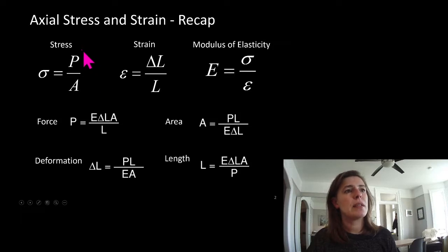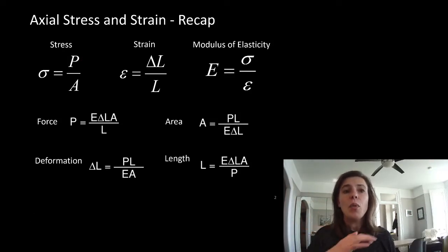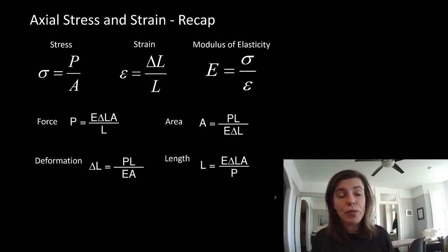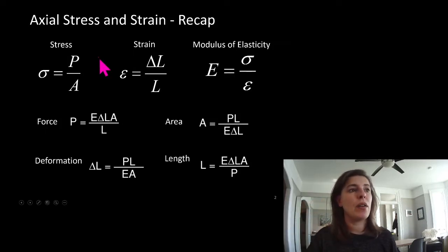Same here with stress. We want to know the force. Last term, we knew we could figure out what the force on a column is. We find the tributary area. We find the loads that are acting on the floor from our load tables for dead loads and live loads. We factor those loads. So if we were talking about a dead and a live load, it would be 1.25 times our dead load plus 1.5 times our live load, times that tributary area that's loading up the column, and we've got our force that's being applied on it.